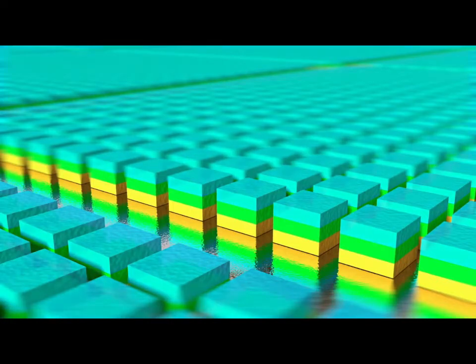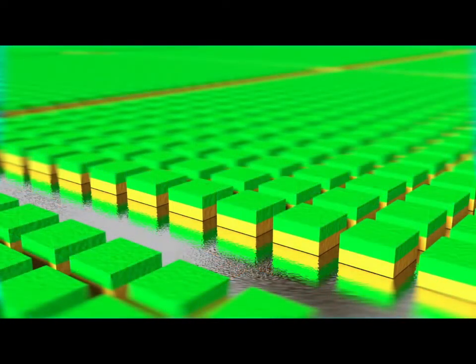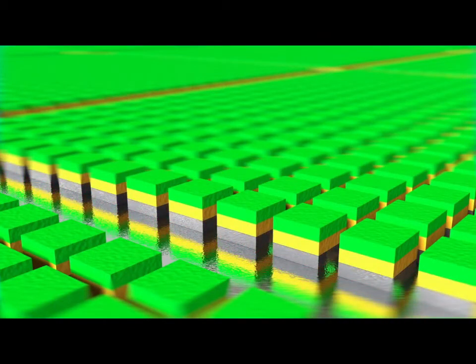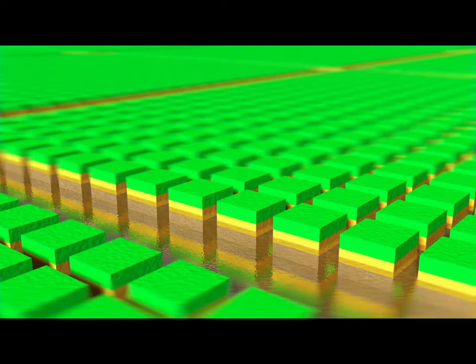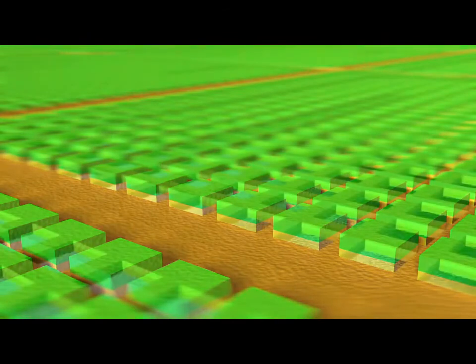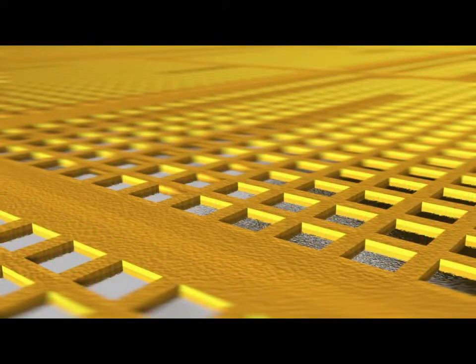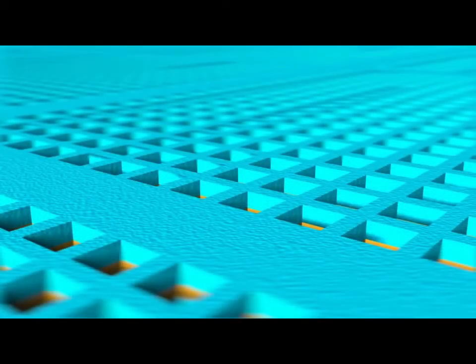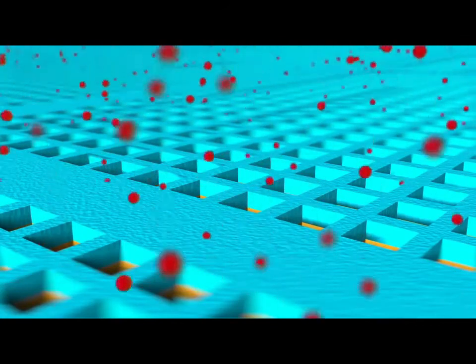Finally, the cleaning of the photoresist and a further chemical etching of the silicon regions. Another layer of silicon dioxide is then applied, which will serve as insulation between the transistors. Etching and grinding processes expose the silicon underneath. Photolithography is used once again in the process of doping the silicon regions for the purpose of protecting the regions which are not to be doped. The silicon regions are treated with either N or P-type doping through ion implantation. This example is one of an N-type doping.